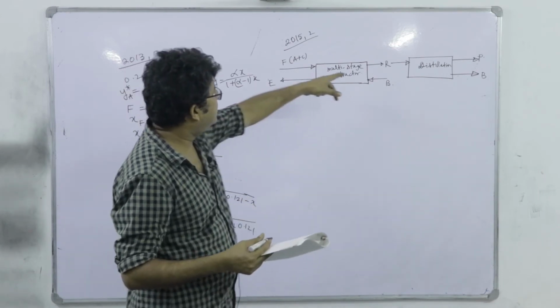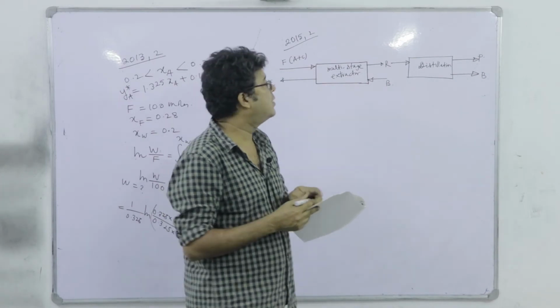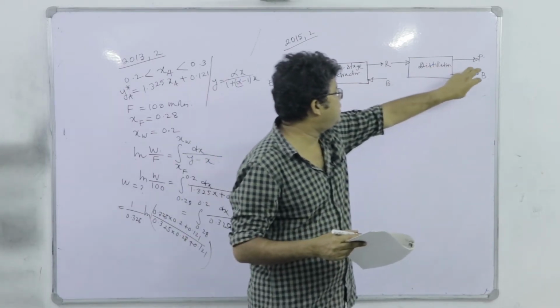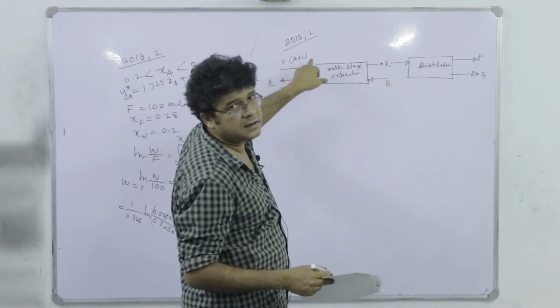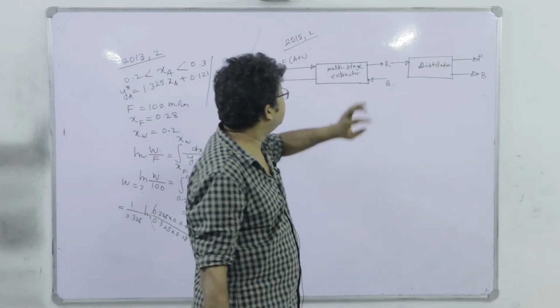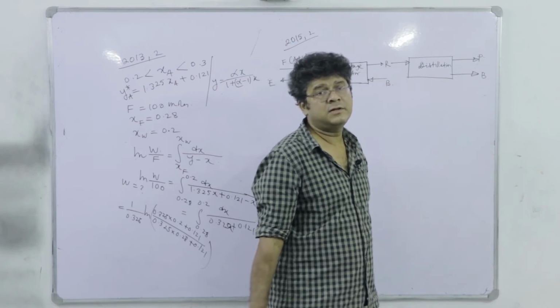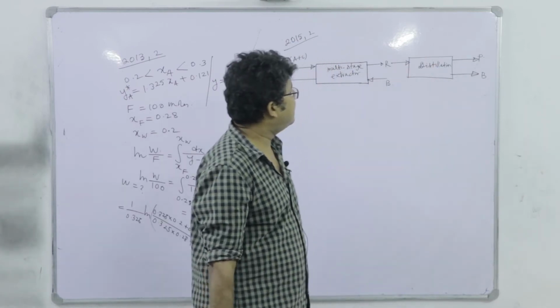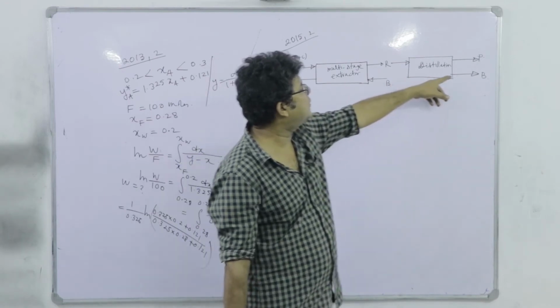Why are we getting B here, if that is definitely not a part of the problem? Because A is the carrier, C is the solute, B is the solvent. A and B are appreciably miscible, so that is why we have a lot of solvent in the raffinate phase, which we have to regenerate back.